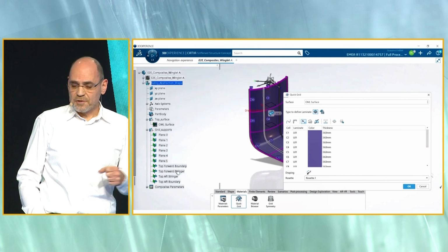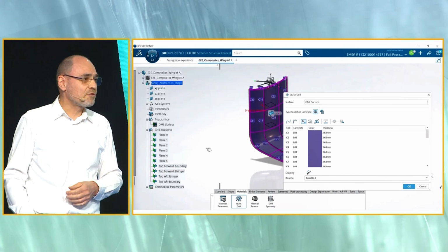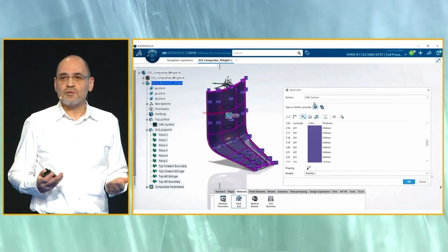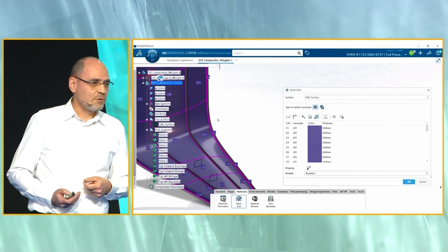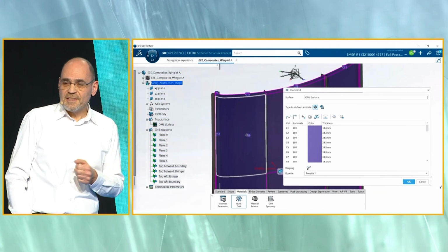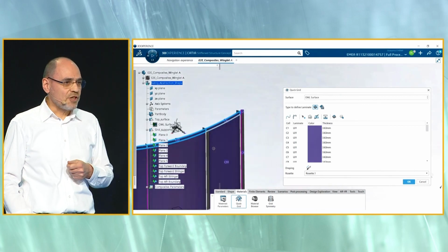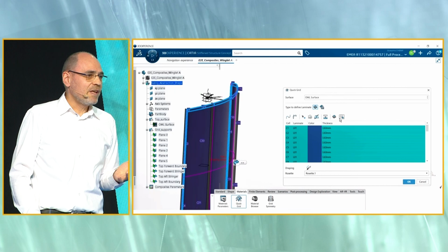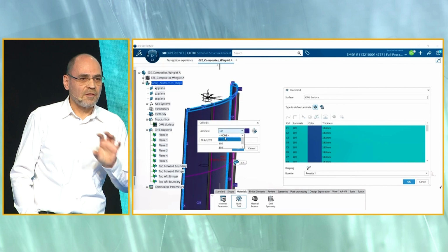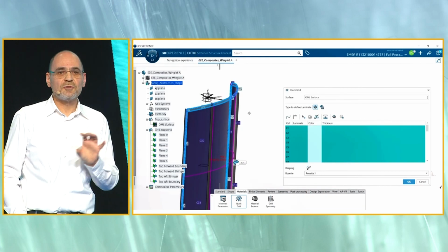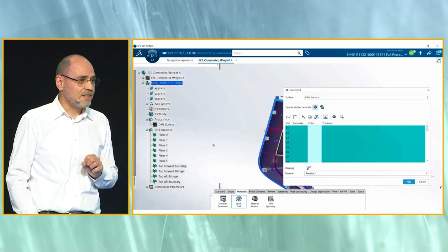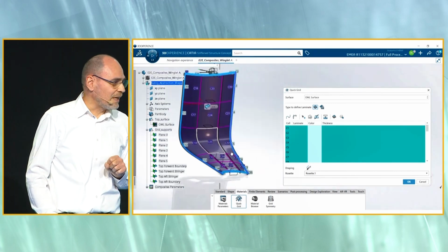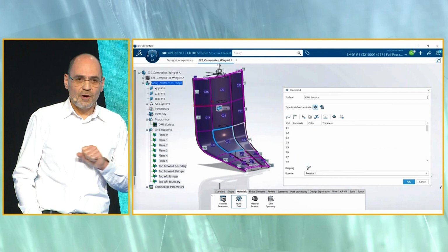He's providing a surface, and you also have constraints like substructural elements that will be assembled to your part. With this tool, the stress engineer or the designer, both can use the application, will be able to isolate locations on the part on which they will be able to define specific thicknesses. That means amounts of material with given orientations.